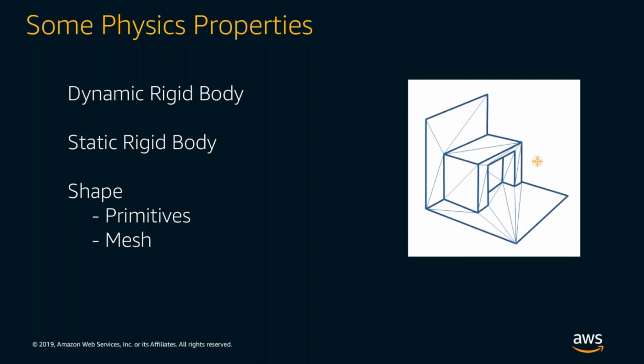Each body, no matter whether it's dynamic or static, will contain one or more shapes in general to describe its spatial extent and collision properties. There are different kinds of shapes available to use, including primitive shapes such as box, sphere, plane, capsule, etc. The physics engine will simply construct these shapes based on the parameters passed in, like half extent, radius, normal vector, and so on. There are also mesh shapes, including convex mesh and triangle mesh.